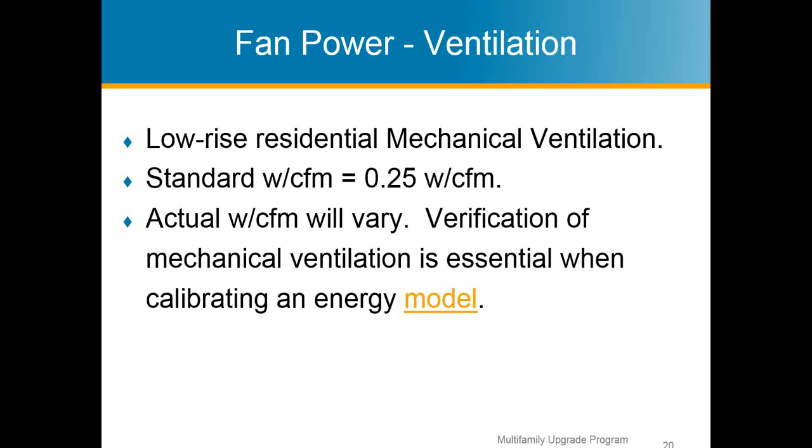The way you can calibrate or verify those things out in the field, on fan watt draw, is you could use your flow hoods and really get in there and figure out what that energy consumption is. That would be definitely above and beyond what's going on in this recalibration here. But you need to just know that the building is running equipment that's not efficient, and that's why you're seeing that billing trend higher than the actual usage in our energy model.